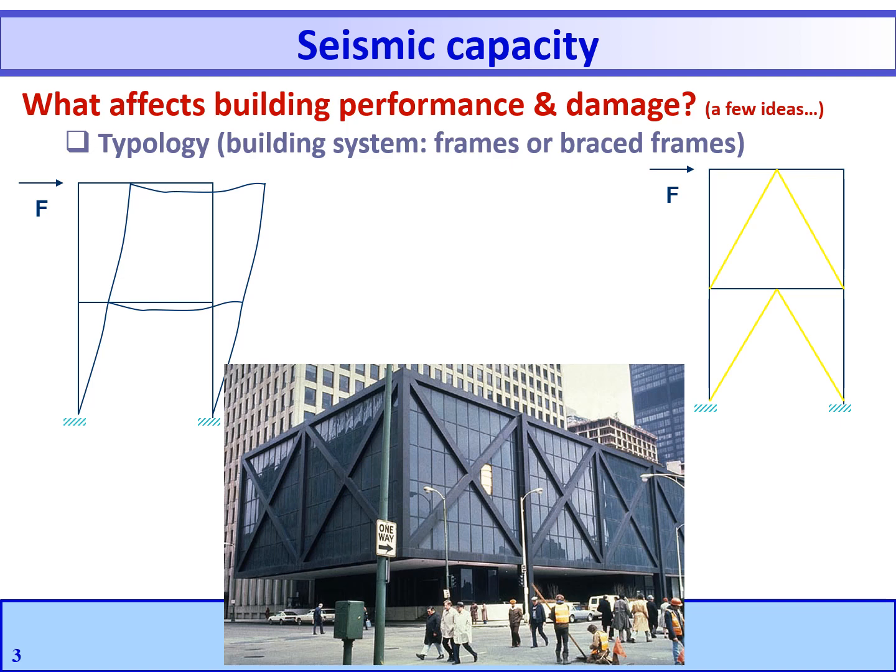In accomplishing these ends through codes, many variables involved in seismic design must be taken into consideration, such as the variability in ground motion, the soil type, the dynamic characteristics, material strength properties, quality assurance, and construction practices.